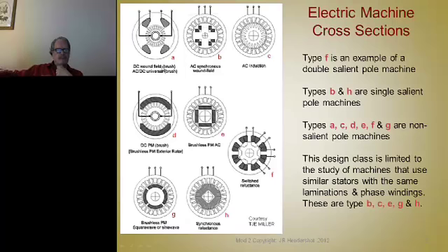But these DC motors evolved into synchronous motors. Remember, that was our second motor. It was an AC synchronous motor. It has a wound field on the rotor, much like the wound field on the stator of a DC machine. So this rotor produces DC current flowing in these coils, producing north-south poles, and then the flux from those electromagnet poles in the rotor links with the conductors in the stator, so you have a synchronous motor.